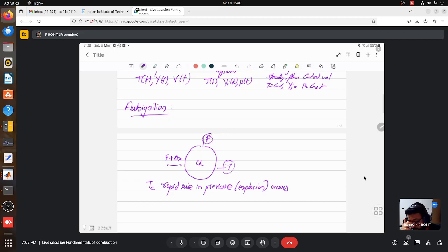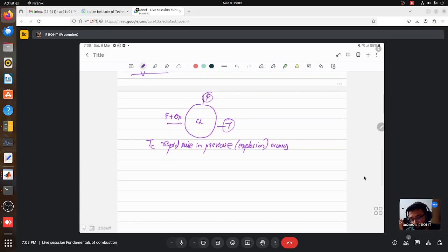This can be estimated by continuous monitoring of the pressure inside the chamber. So you have pressure sensors that can measure the pressure within the chamber. So that particular temperature at which you have a sudden rise in pressure. You might remember the diagram that was shown between pressure and temperature at the time. As time progresses, the pressure will be slowly, gradually increasing within your chamber.